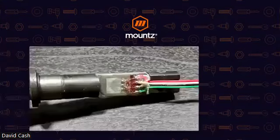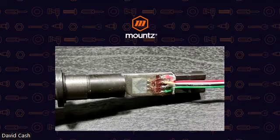So if we look at this in a real life application, we have our strain gauge that is laminated onto a piece of stock. And as that stock gets turned or allows torsion and there's that flex, as we measure the resistance that happens within that strain gauge, that is going to give us our value that we can correlate to the actual torque value.